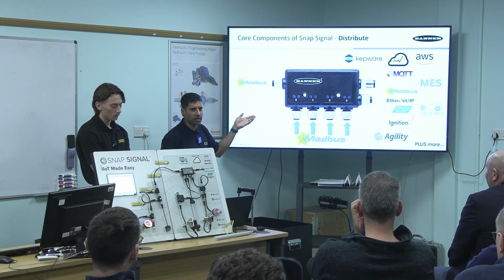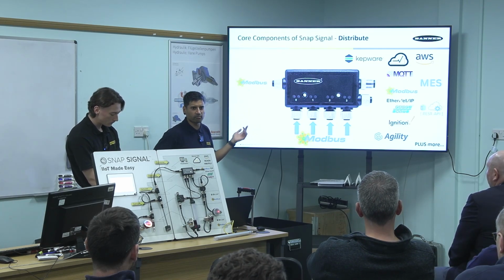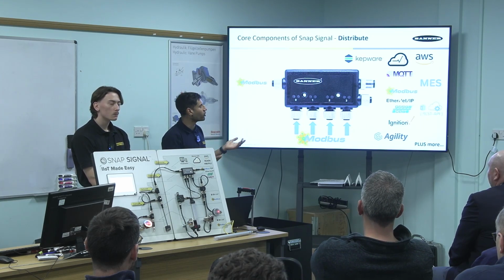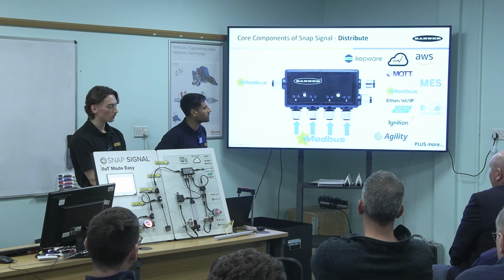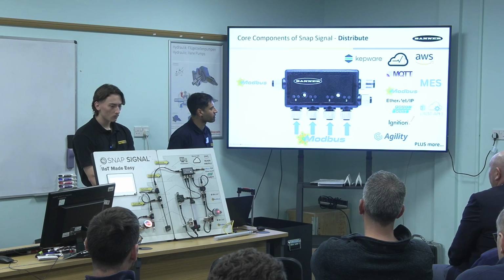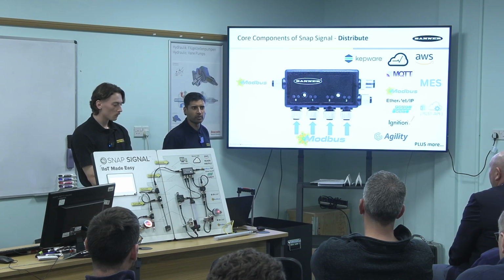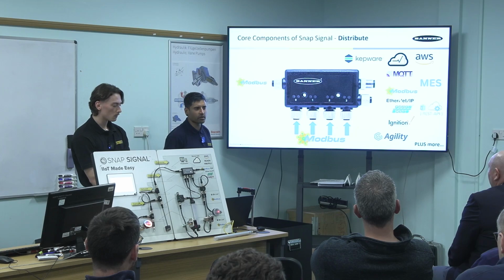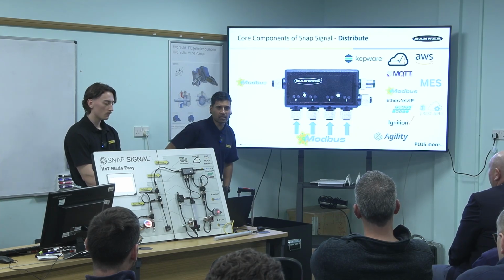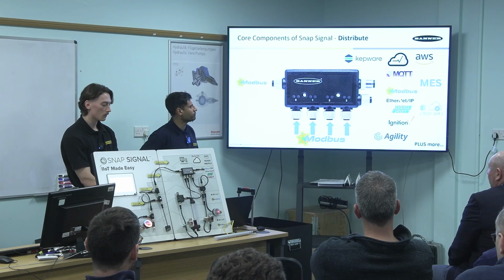Being Modbus TCP, all you need to do is give the IP address and the Modbus register, and it knows what device we're speaking to. And Modbus TCP, Ethernet IP, Profinet, that's predominantly the sites we go to. Someone's either going to have a Siemens PLC or an Allen Bradley or Schneider, and you can easily integrate it with these manufacturers.